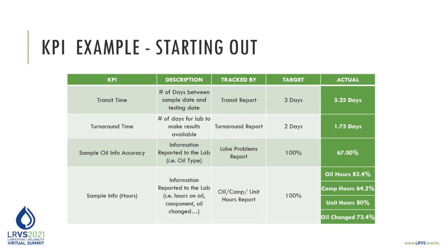Well, how about sample info hours? Can't tell you how important that is. That's information reported to the lab. Lets you know how many hours on that oil and a component, or maybe even when the oil was changed. Oil analysis labs can tell you that. We're going to have a target of 100% compliance with that. You can break it out as well: look at oil hours, component hours, unit hours, oil change. Those are 4 different things we can actually measure. It's just an example of maybe what the particular customer had done. They didn't hit it on all cylinders, but